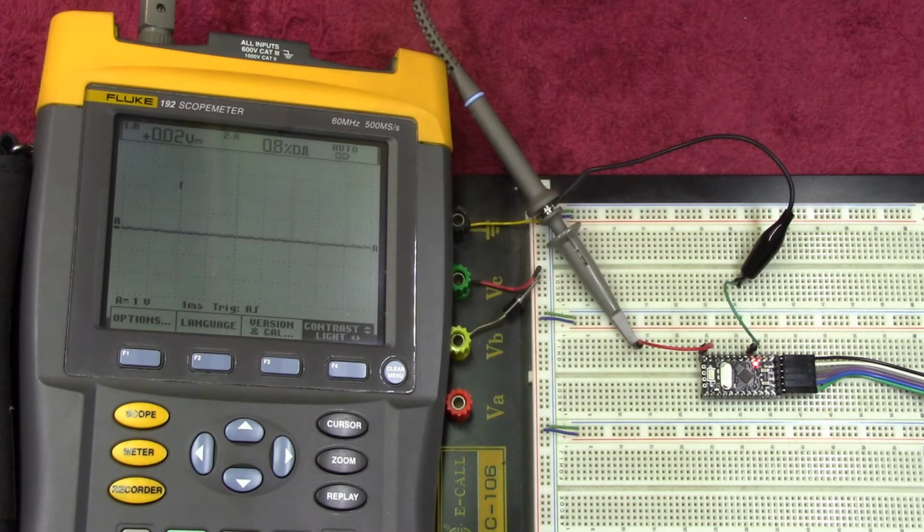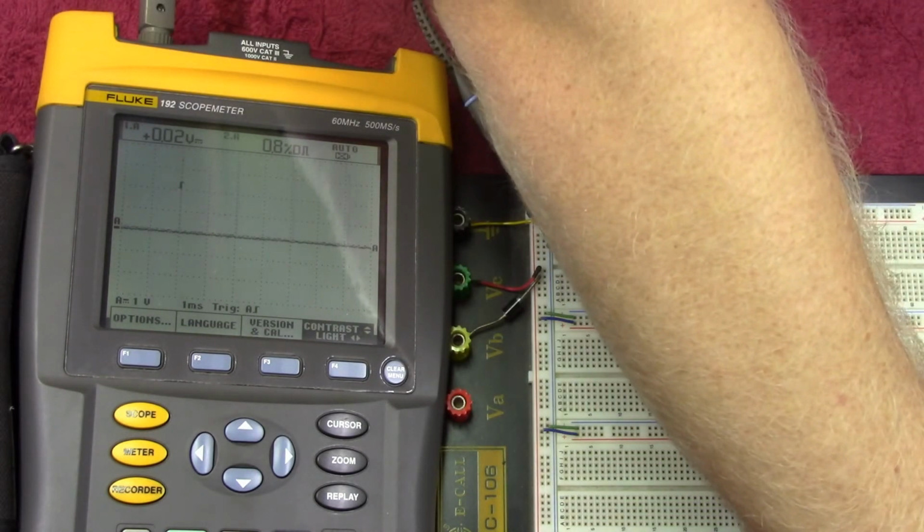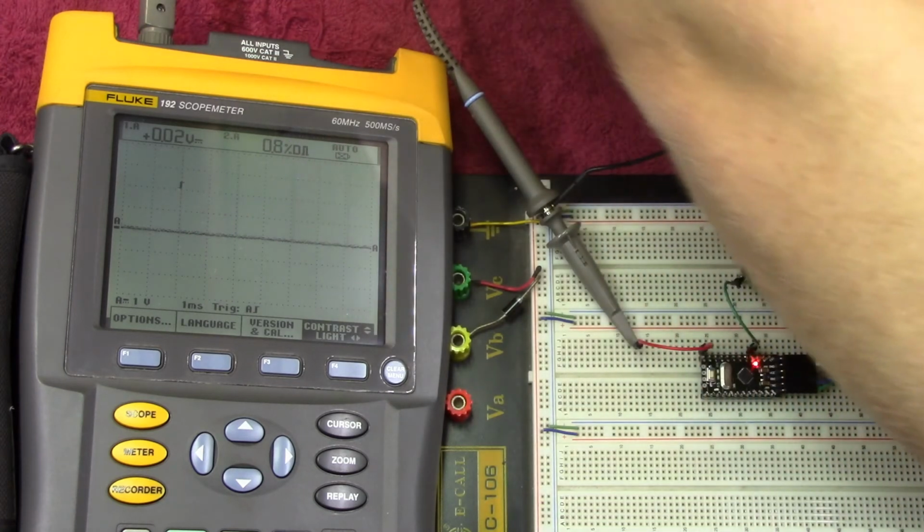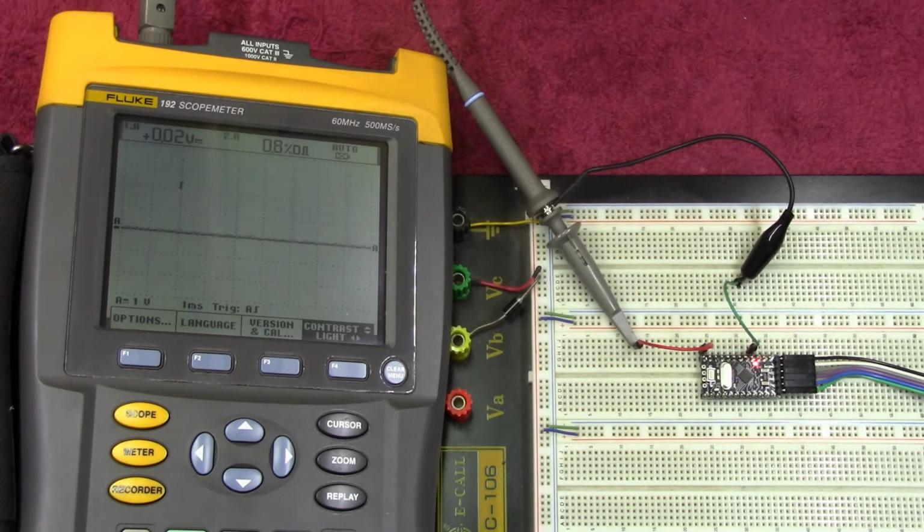Now if we ran that to 10%, 25.5 should be expected. So we'll upload it at 10% duty cycle. Now 10% of 3.3 volts, you'll get it now. Okay, we're running at 9.8 or 10%, and 10% of 3.3 volts is 0.33 volts.